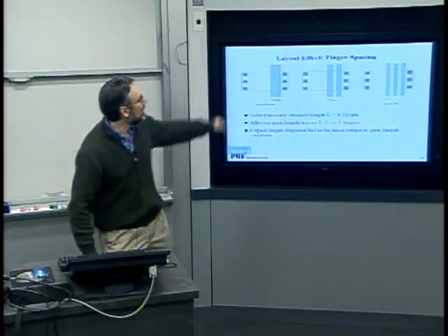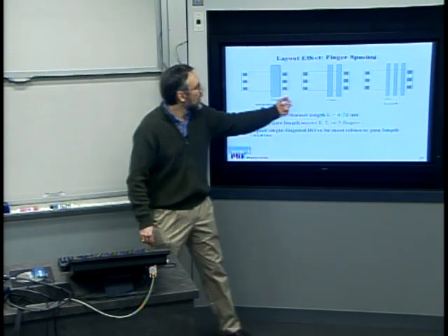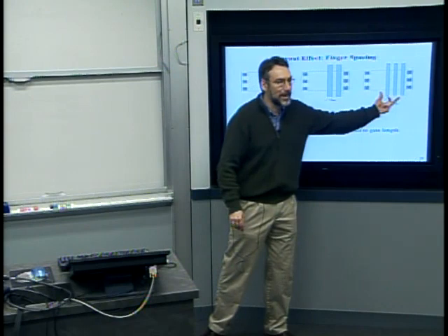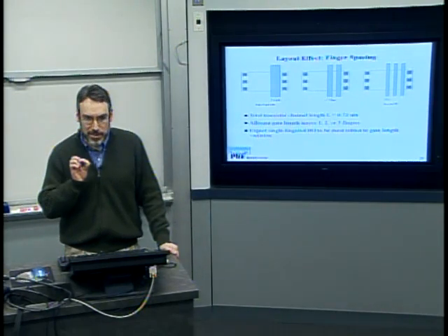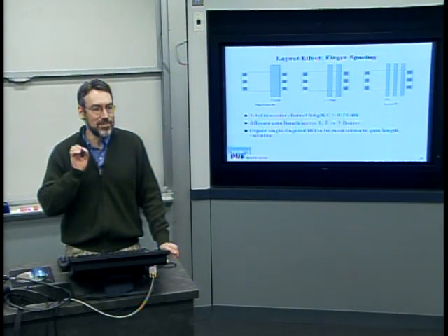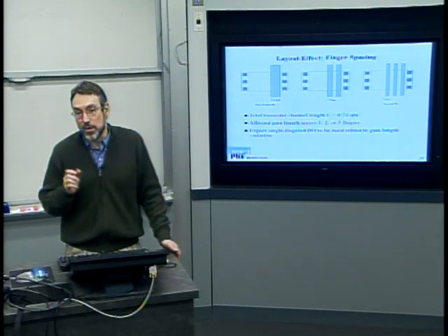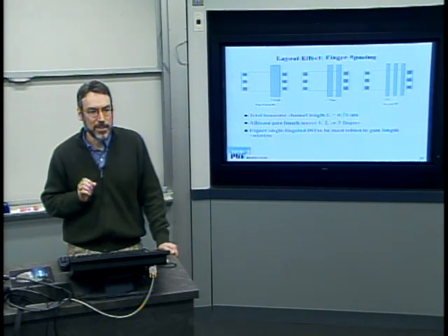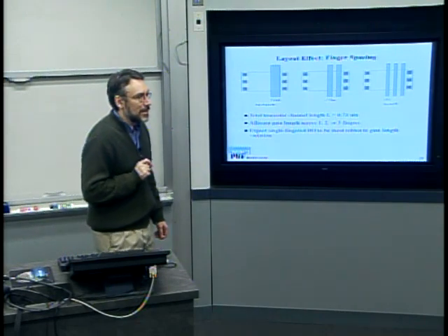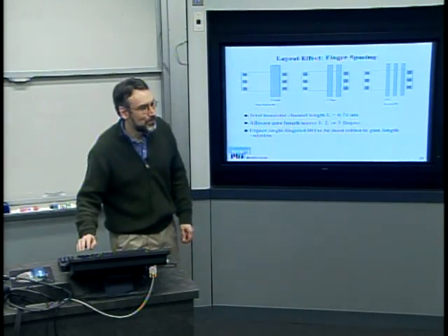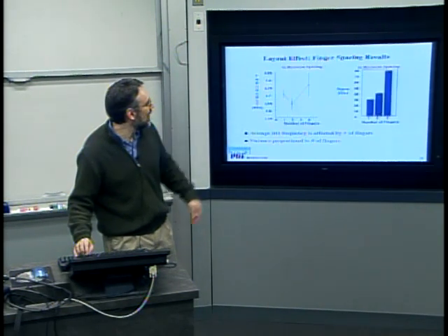An interesting effect is if we take that single gate electrode, and split it up into 2 or split it up into 3, and then look at the effect on ring oscillator speed offset and variance, what do you think we're going to see? We didn't know, so you may not know. But, yeah. Probably see more variation in the 3-finger one because you have more edges. Right, you have more edges, and that's exactly right.